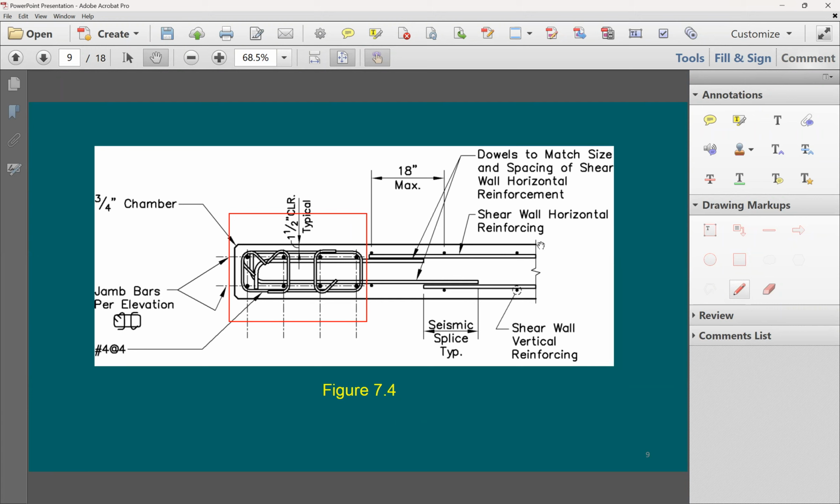It says minimum reinforcement for a 16-inch thick shear wall in the horizontal direction is nearly. Now, this minimum, without having any shear demand, means that I need to apply the 0.0025. Let me go back here and show you what I'm talking about. You see this here, minimum shear ratio? This is regardless of the amount of shear demand and the strength that you need to design for. If you have any shear wall, this can be your minimum reinforcement. So in this example, it says minimum reinforcement for this 16-inch thick shear wall in the horizontal direction.